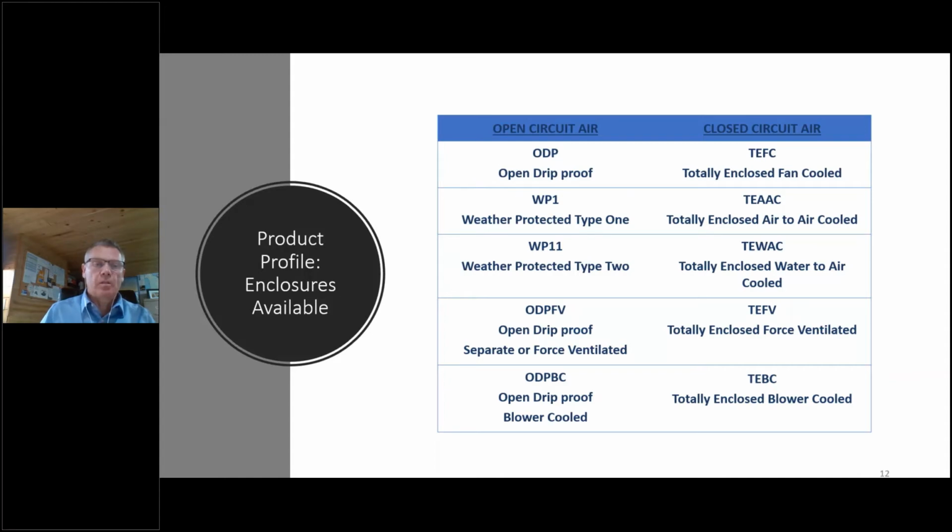They tend to be a lot less maintenance, and they tend to be the workhorse. Now, people ask, when do we transition from a TEFC motor to an open motor? It's going to transition differently between manufacturers, and sometimes that's economies of scale or manufacturing capability, and it may even be customer preference. It could be part of the hard spec.